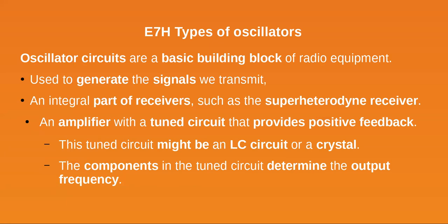In essence, you pretty much need an oscillator, even if it's digital, and you're digitally generating your VFO and beat frequency oscillators, all those kind of things in the digital domain. You still at least need a clock signal for the signal processor. So even in the digital one, you're going to have an oscillator.